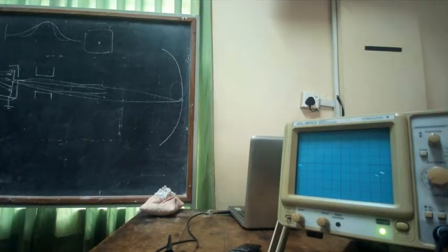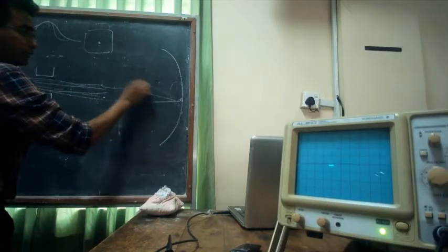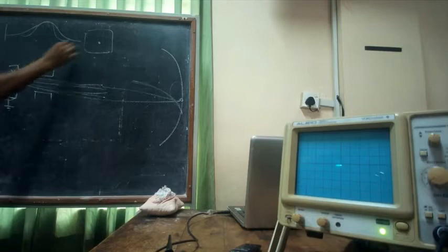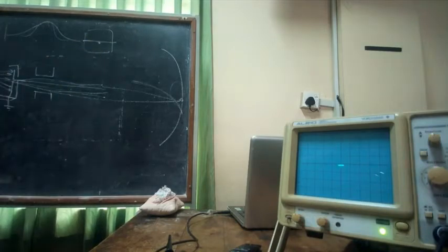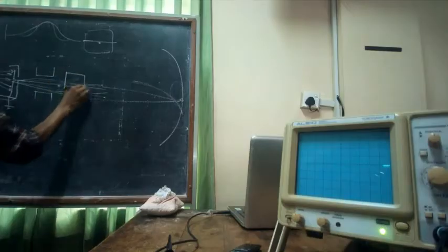So now my objective is to control it on this screen. There are two dimensions, up and down and left to right. Now if I want to control it left to right, in this direction, right? I have to apply an electric field in this direction, that is horizontally, so that it gets deflected in that direction. So therefore, I have what I call the horizontal plates.